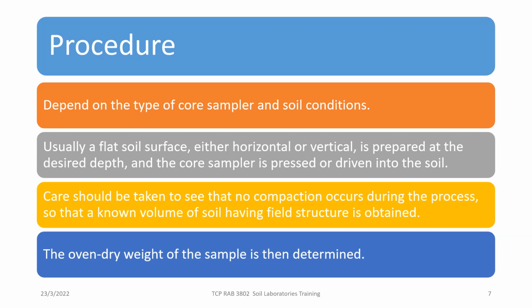And normally the bulk density should be taken for each depth, because some soil layers can have a good bulk density, while others maybe have a higher bulk density. This depends on the layering of the soil profile, as we discussed, I think, yesterday.